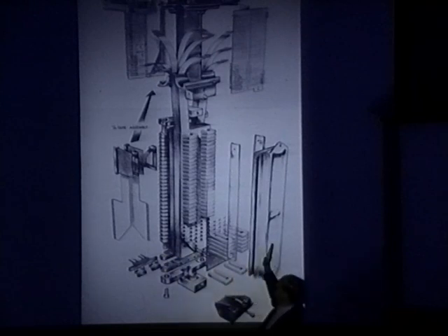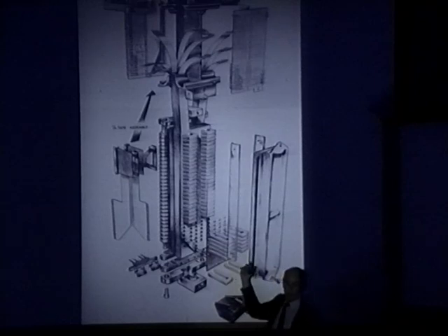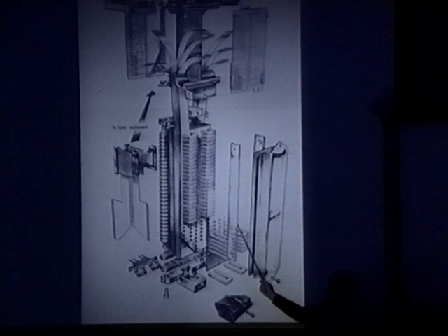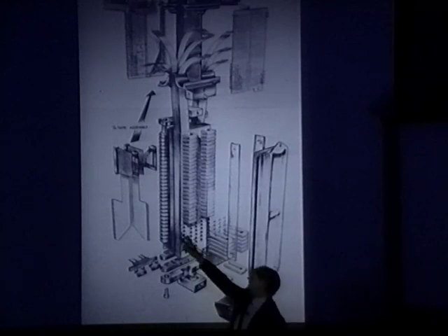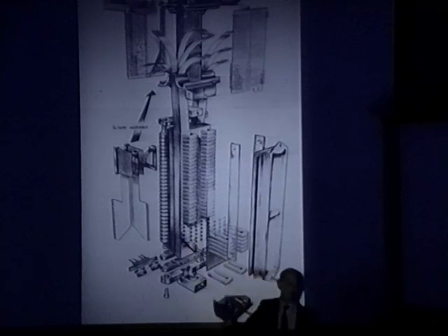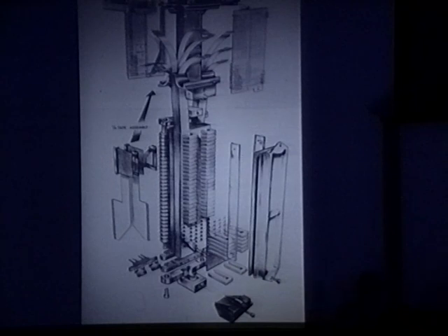The U cores are pressed in place by another carrier there, a pressure plate there. Now, we can only get 128 tapes. Each tape can carry two drive wires, one on either side, there and there. So 256 words per module. We modularized the array, provided up to 16 of these modules to make a complete array.